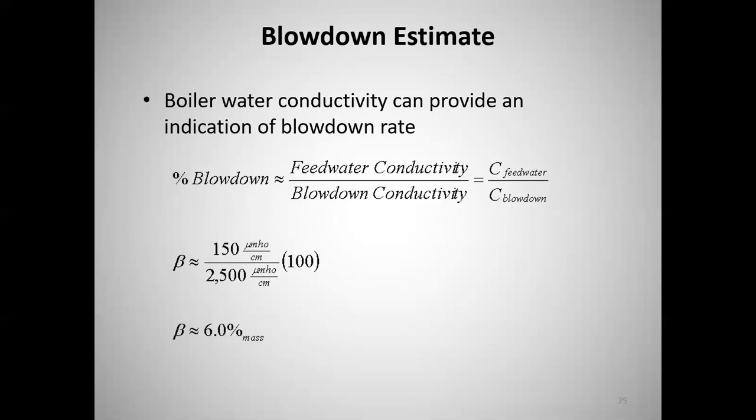You get no current, and so you get a reading of 0. If you stick it in water that's got a whole lot of minerals, you get a lot of current, and it transduces that and gives you a conductivity reading. So it's pretty easy to measure conductivity. It's harder if you have to do some sort of a chemical test, take this stuff and put drops in, or evaluate it somehow or the other.